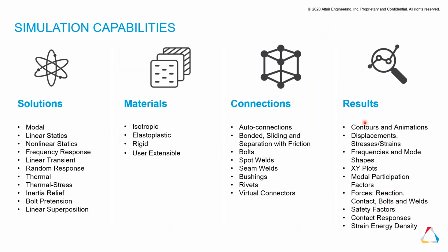Okay, so what can we do in SimSolid? Here are some of the simulation capabilities in SimSolid. We can perform modal analysis, we can perform linear statics, and we can even perform non-linear statics. So if you have a non-linear context, non-linear materials, non-linear geometry, we can do it here in SimSolid as well.